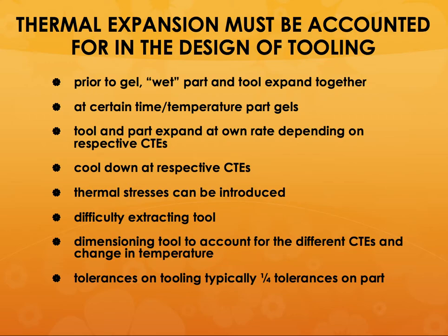Typically, the tolerances on the tooling are one-fourth the tolerances on the part. I mean, this is a very abstract rule of thumb, but it may not always be true. But that's the typical number that we work with.